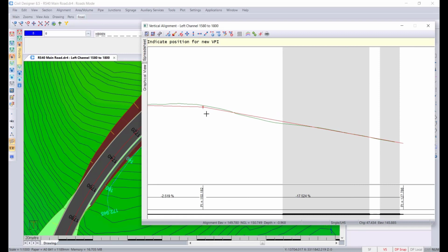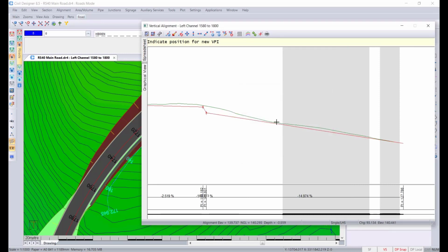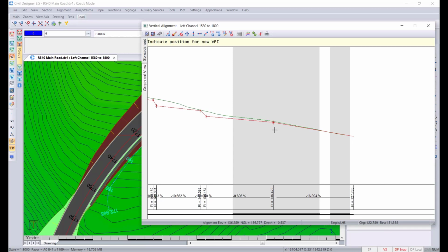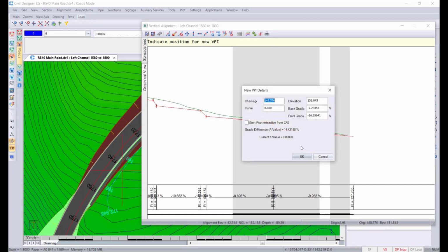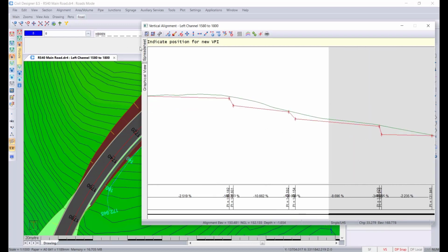So you then want to go down again and across, but care needs to obviously be taken not to become higher than the main road itself, because that would defeat the point of collecting the water, I guess. So we're trying to create these energy dissipation along the route. The percentages, don't quote me on them. You'd need to read them up and use whatever your local guidelines are.